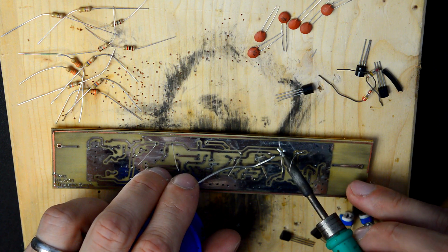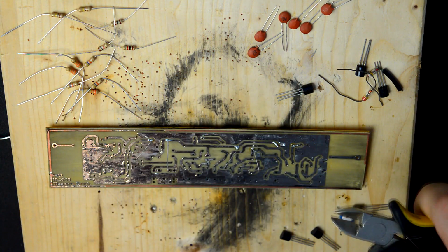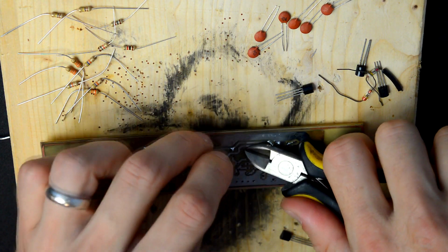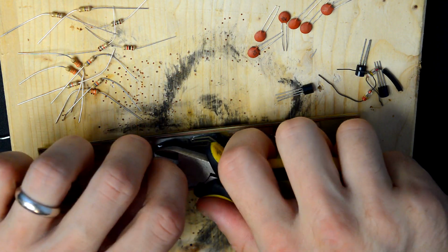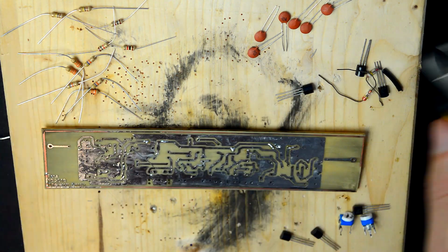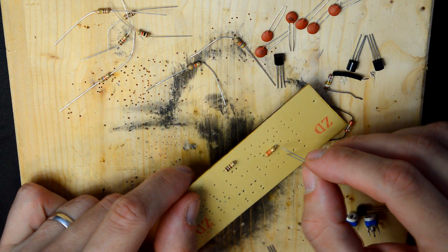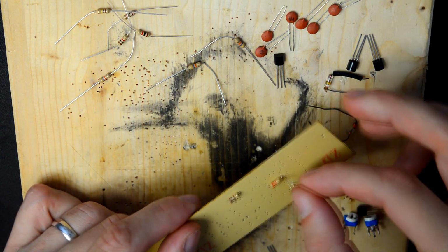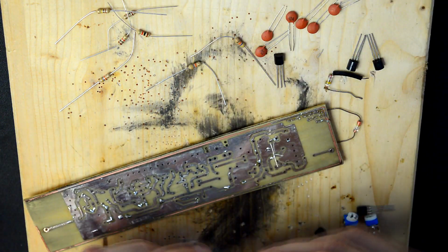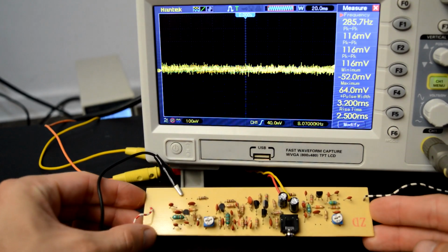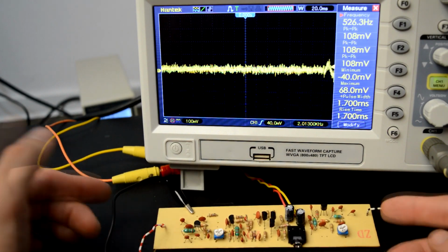But for this thing, the Theremin, small and compact is not really a good thing. I mean, you need physical distance between components, since you're working with tiny variations in capacity, which are below 1 picofarad. The whole circuit I'm building could fit in a matchbox, but then it just wouldn't work. So for this particular application, through-hole components are more useful. So this is the assembled circuit, and let's go ahead and look at some of the waveforms that we've seen